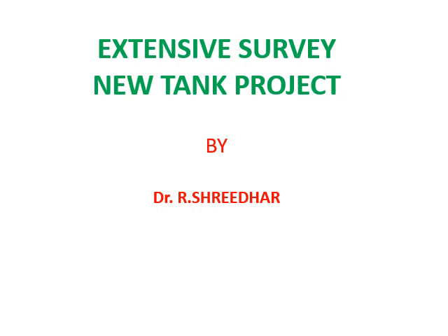You might have done the reconnaissance survey for the bund, where you can locate the catchment area, and for which you have to collect the topo sheet, because you can't do the survey for the entire catchment area. There is a wrong feeling that when we do capacity contours, from the capacity contours that are generated, we can calculate the catchment area. Actually, it is not so. So many of the students do use the same capacity contours for the catchment area.